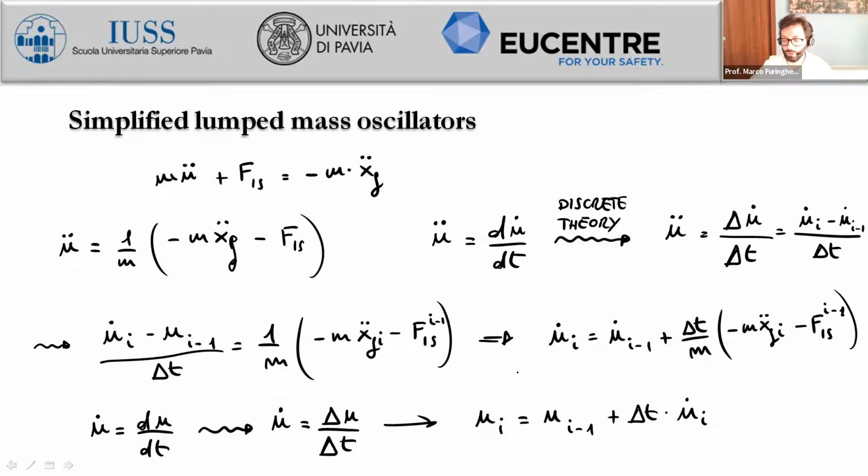So now what we have to consider is actually the definition of the isolation force. Okay, so we will have to consider the different behaviors that we have, and then to combine them. Maybe if we have hybrid systems, we can actually try to combine flat sliders together with linear elastic oscillators for rubber bearings, rather than elastoplastic with hardening for lead rubber bearings. Any questions from this?